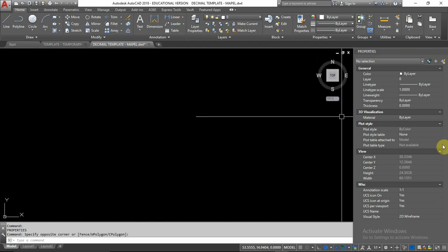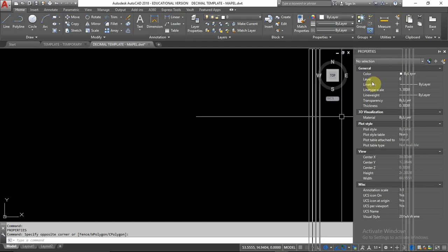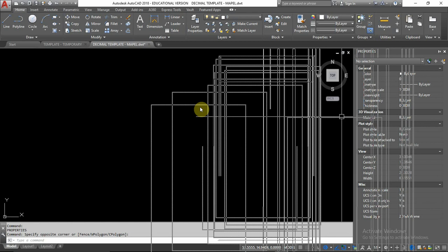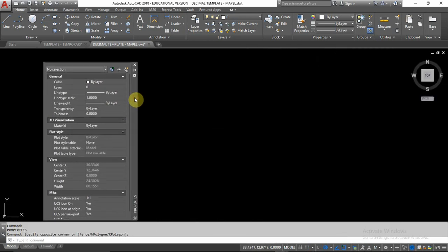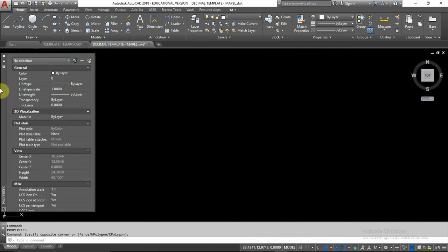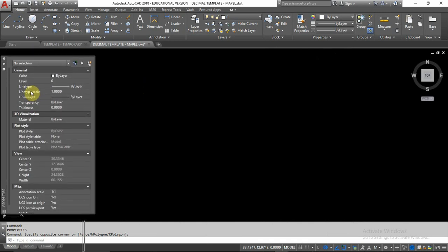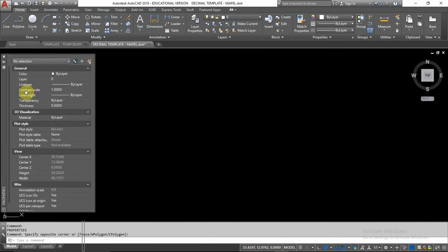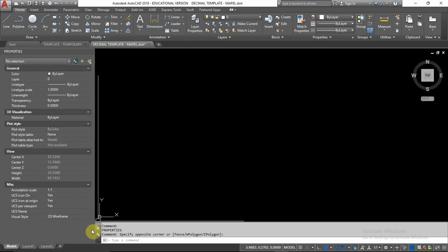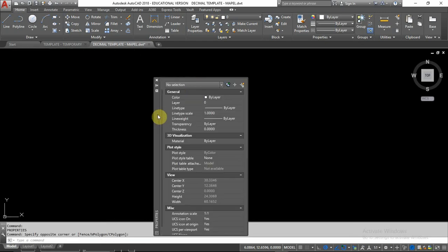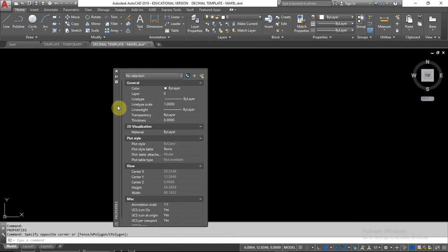If I want to move this again, this is called docked, or docking. If I don't want it docked there, you need to grab that bar. And notice I can finally pull it off, and there it is. I can also bring it over here. Currently the bar is on the right. If I bring it over to the left, notice it switches, and the reason for that is that it's snapped to this left side, but if I go farther, there it is to dock, and my command line, everything pops over. And again, this is at the top. Even with it docked, you can have the auto hide feature on.